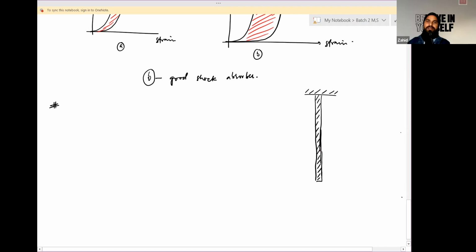Good. Suppose if you consider this particular strip, for this particular section, there is some amount of wire behind it, which must be applying some force to this segment by gravity to increase its length. This is called extension in a wire due to its own weight.